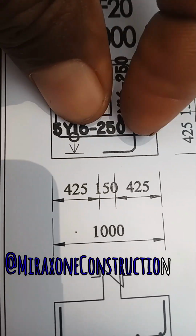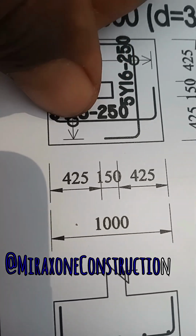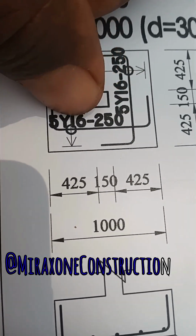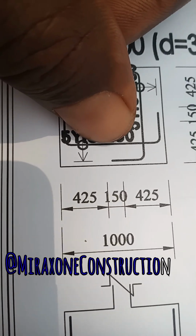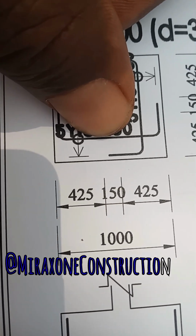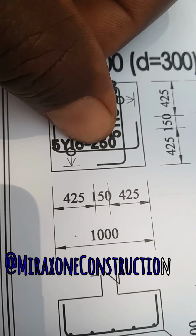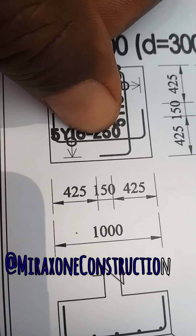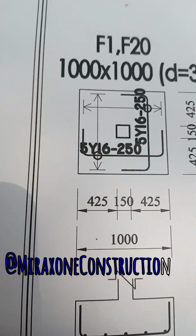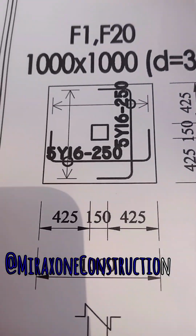So this 250 here indicates, I hope you can see it, 250 millimeter. It is the spacing of the reinforcement. When you are placing the reinforcement, you have to give a gap from one reinforcement to another. Let me analyze it.